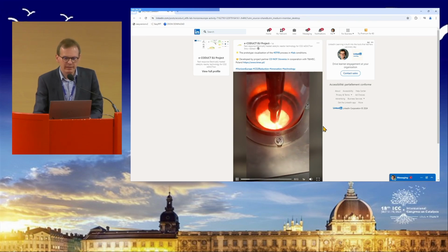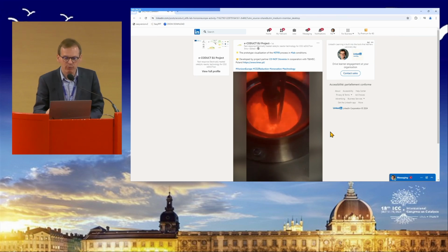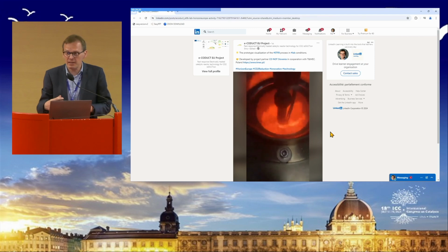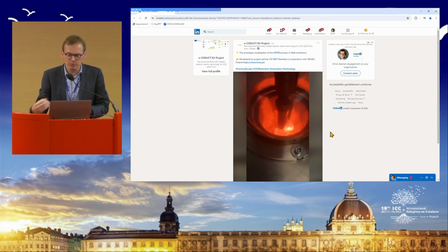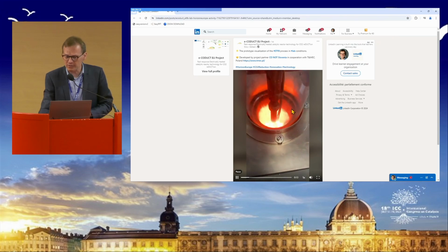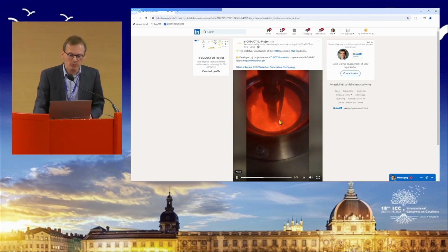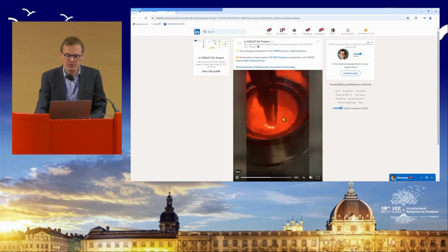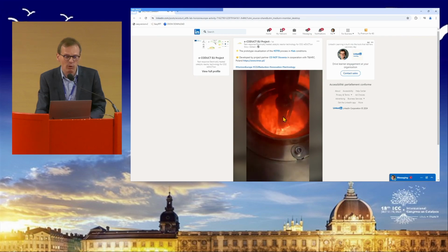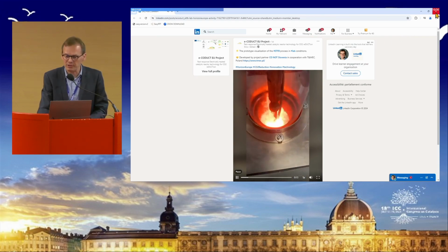So like this you get an idea of how the fluidization goes. You see the bubbles getting through, ensuring that the bed still remains a continuous phase, so that there is a current between an outer electrode at the side and the center electrode. And you see how high temperatures in such a reactor system can effectively be reached, so quite useful for highly endothermic reactions.